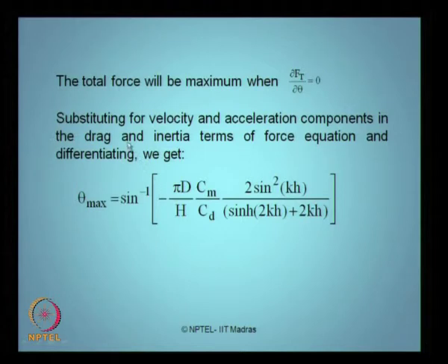So by substituting the velocity and acceleration components in the drag and inertia terms of the force and differentiating it, I can find the maximum angle at which the force remains maximum. I will compute the maximum angle, substitute it back in the force equation and find the maximum force in the given member.